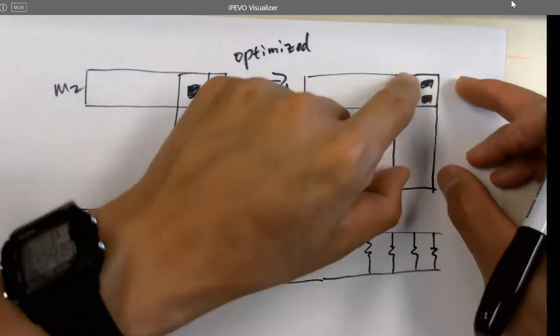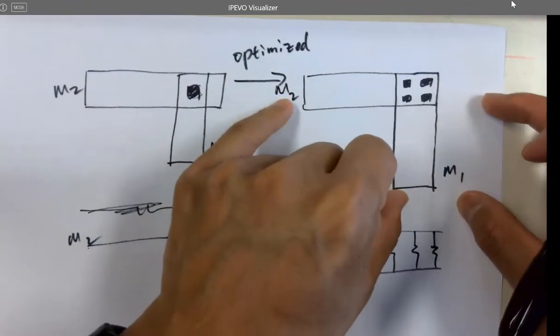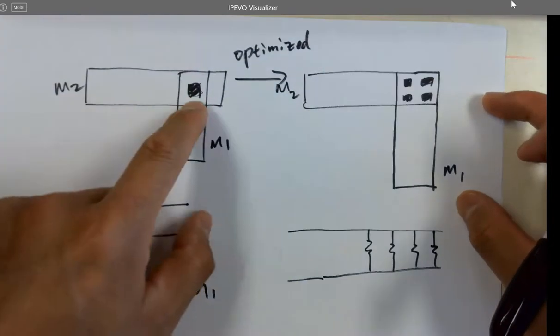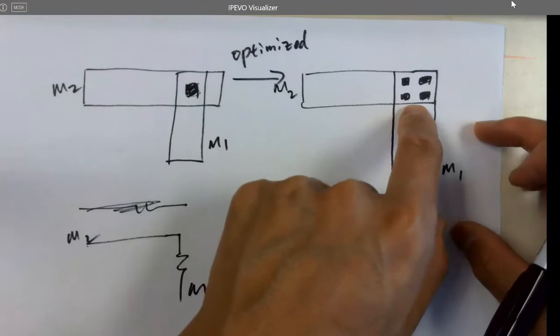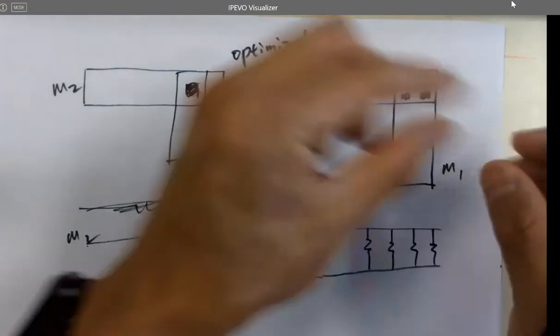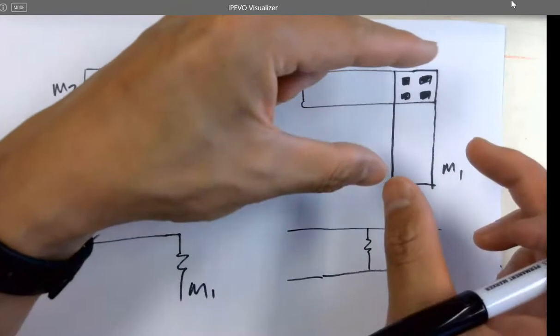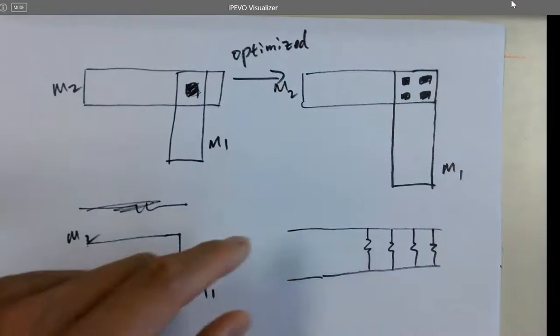So whenever you see a via between M1 and M2, the purpose is to make the connection between these two metal layers. But instead of using 1, the software is going to directly draw 4 here. You don't have to do it yourself. If you have a pretty wide metal trace and you make the connection, it's going to generate multiple vias. You'll see that.